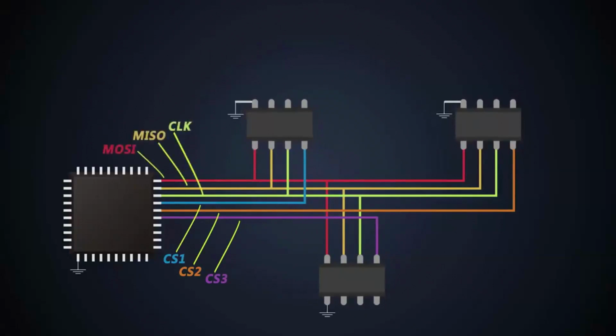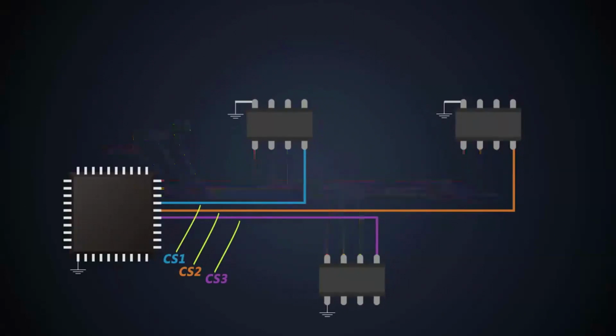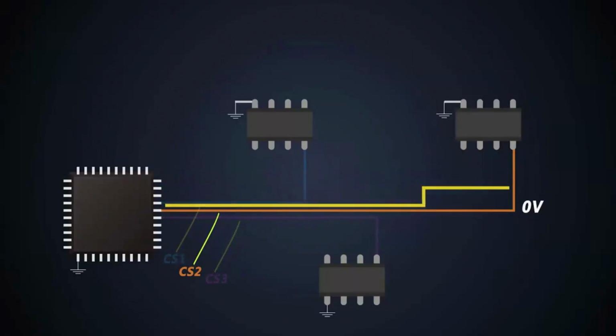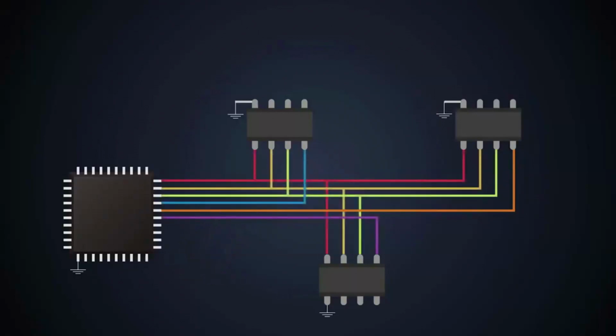So, if you see, this is the limitation of SPI communications. The number of GPIOs restricts the maximum number of slaves. This chip select is an active low signal. Generally, it is pulled high, that is at VCC level, if the master and slave are not talking to each other. When a master needs to communicate with a particular slave, it will pull the chip select line to ground, which notifies the particular receiver that the master wants to send the data.